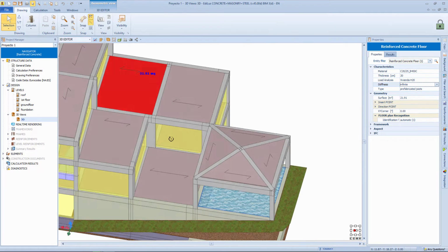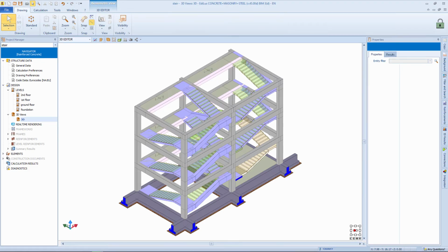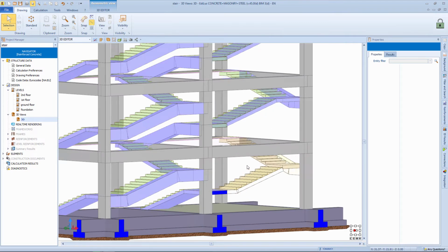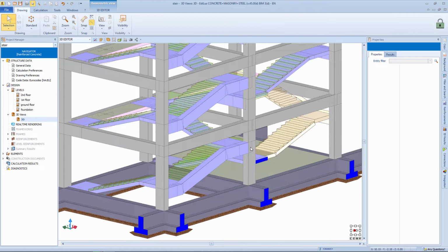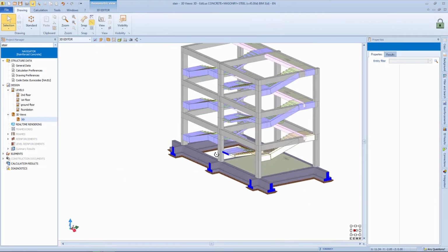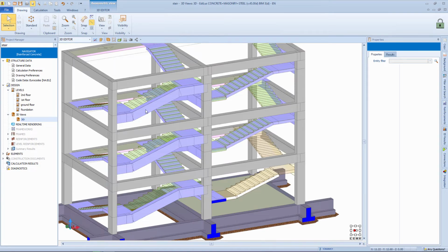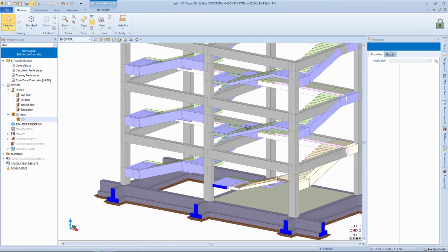Another critical aspect of modeling is the stair object. A common error in modeling this element causes structural problems. Let's look at the case with an example. We open a file where we have modeled a simple structure, which supports a series of stairs of different types: a type of inclined slab, a beam embedded to the left and a beam recessed to the right. The first thing is to observe the structural model, since the view of the structural model helps us to quickly understand if these stairs are well connected to the structure.